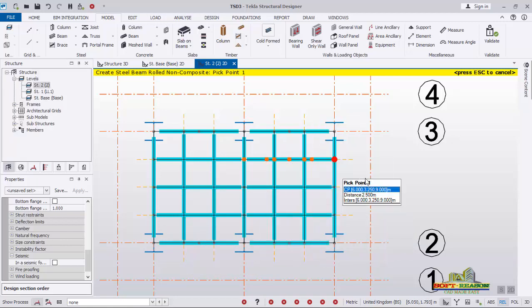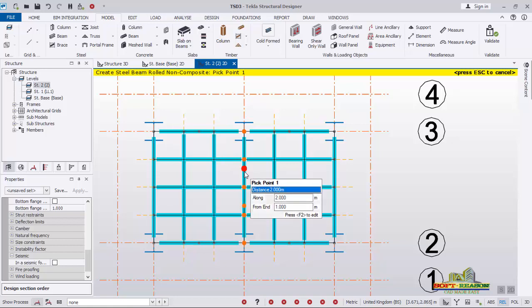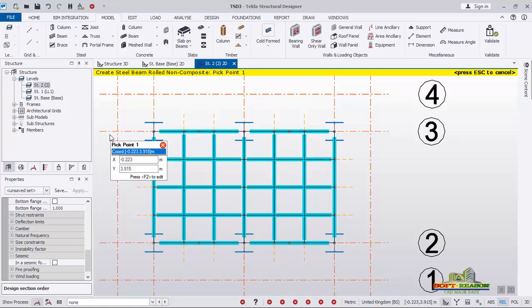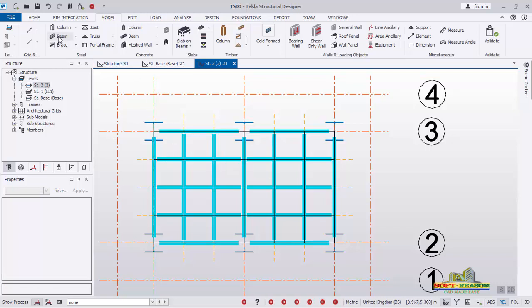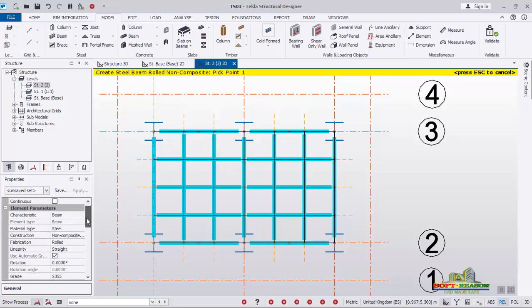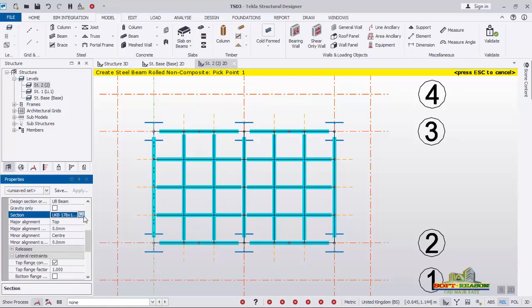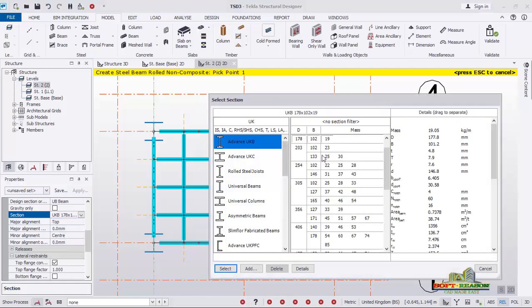base of the tank. All right, so after having that done successfully, we will escape the commands, go back to beam again, and then this time around we will still be considering UKB, but it's not going to be this size. So select get to new. In the new dialog, you can be able to choose this size 152 by 87 by 16.